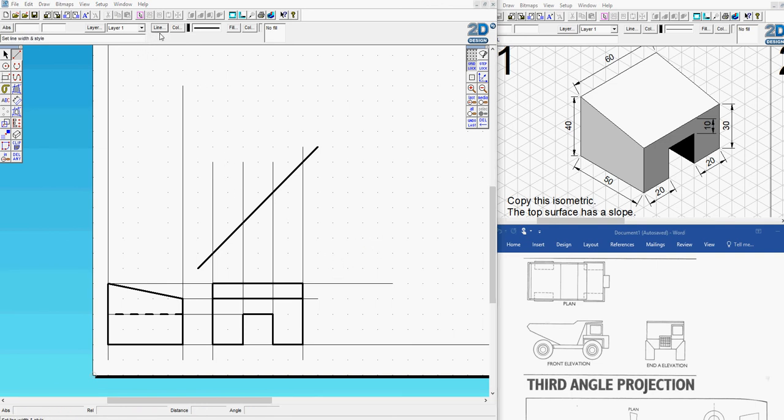I'm going to go back to drawing in construction lines, and wherever you've got a vertical line crossing this thick line, you take it across. You take it across to this view. So that one goes across, that one goes across, that one goes across. So I've taken all these lines from this end elevation up through the 45-degree line and managed to take them across here. So it means you don't have to remeasure anything. And can you see that the plan view is starting to appear here, somewhere in there.